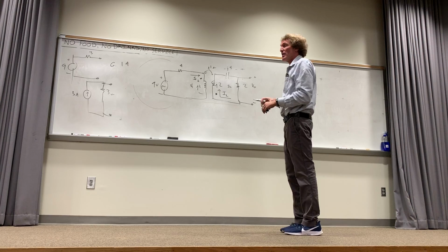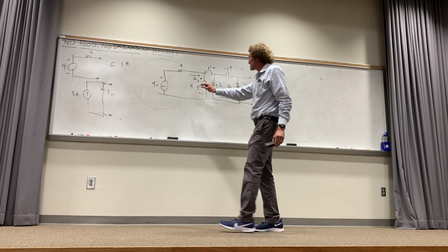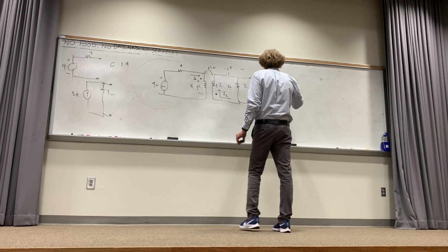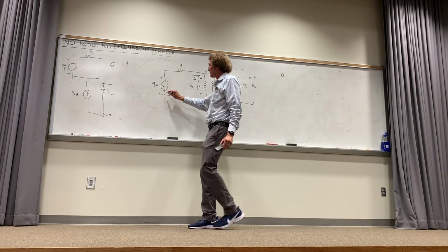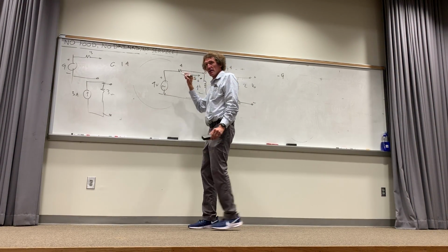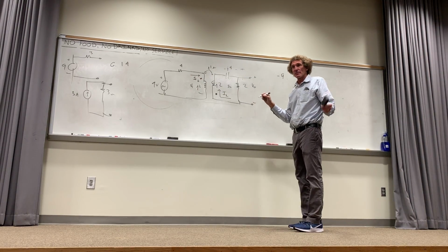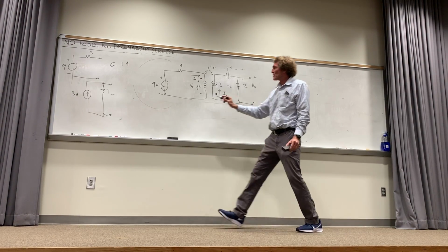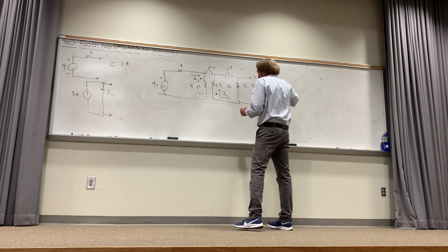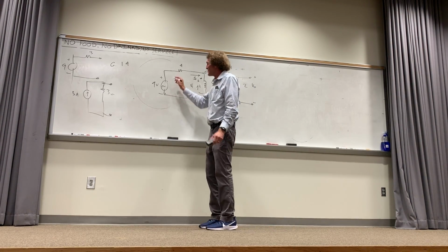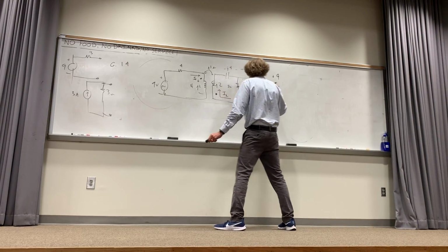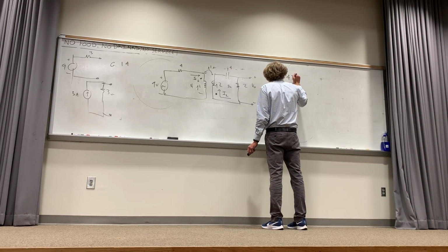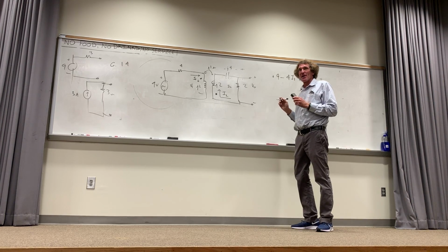What happens here? Now work at the primary side first. Let's do this equation. What do we get? We're going to get minus 9 if we start here, right? And I'm going this way, correct? Come on, work with me. Are you right? Was it minus? Well, because I'm going to, I'm sorry. Yeah. It's not actually. Plus 9, sorry. And then it's going to be minus 4 times I1. Y'all see that? Thank you. I'm glad you catch it.